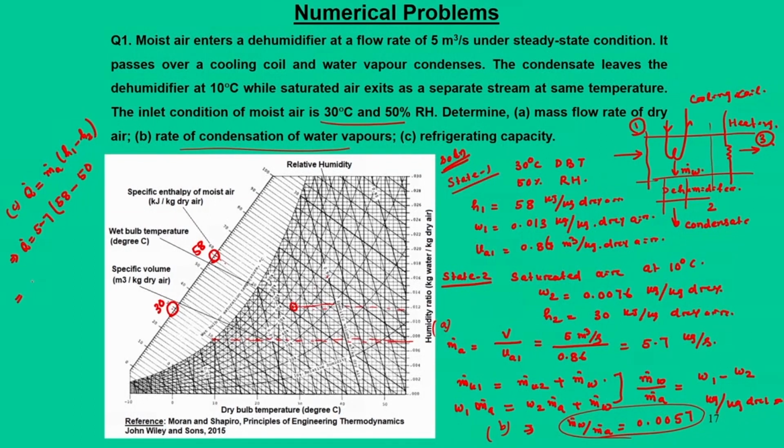So, this means Q dot is 159.6 kilojoule per second, or Q dot can be written as 159.6 divided by 3.52. So, that is 45.3 TR. So, in these terms of refrigeration we can find out.